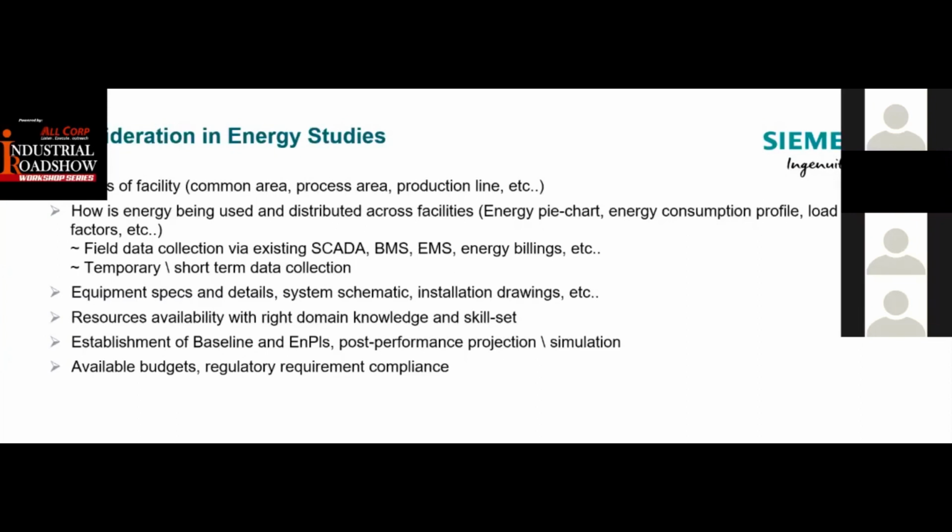For field data collection for level 2 audit, and sometimes in some locations, I will be open to also using BMS data or SCADA data. But the condition is that we need to verify whether all this instrumentation or data collected from the field site is actually logical or realistic. So this will be some form of what we call validation of data before you actually use the collected data for analysis.